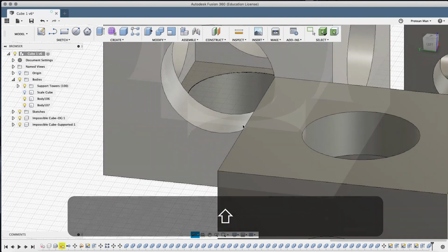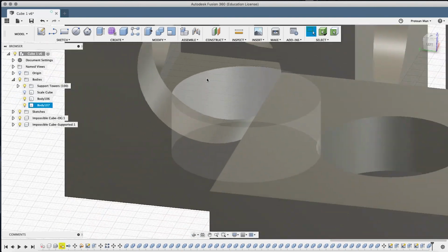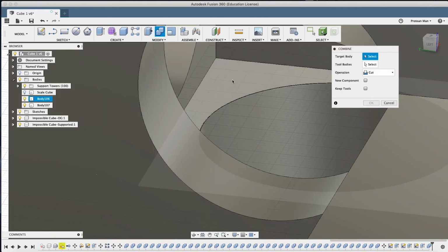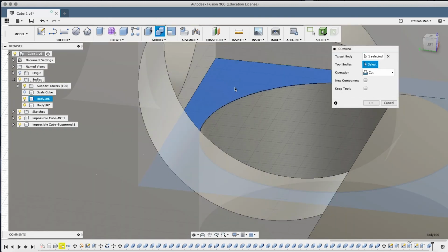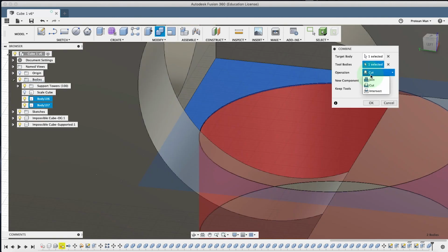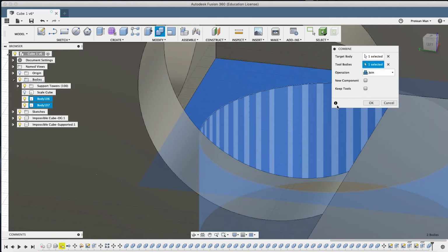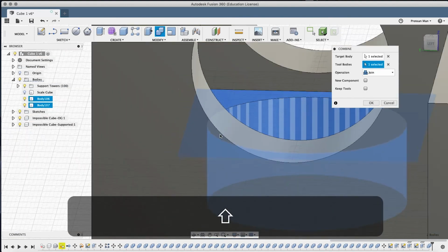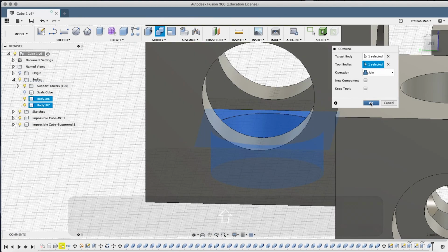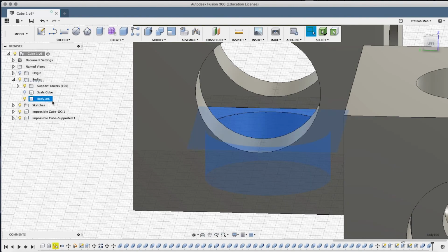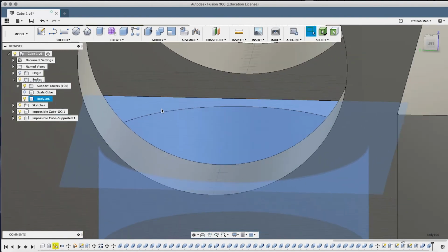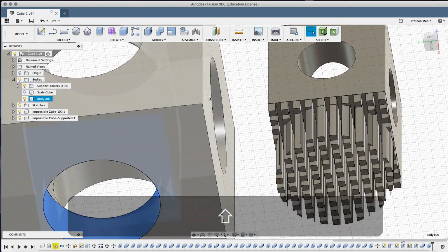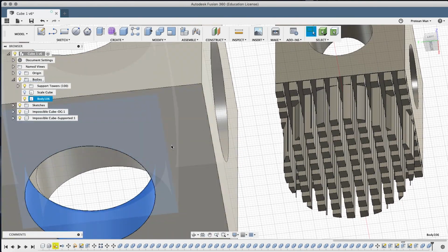Okay, next, let's just for fun, select your inside new square, the bottom layer. Select your very thin layer cylinder. Join them together. Select them both. Make sure your large cube is not selected. Join them. When I click them, they will be one object, one body. So here we go. What this has done is made a cutout for our towers.